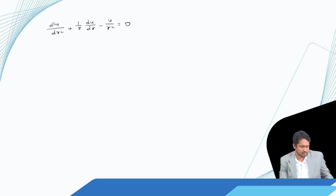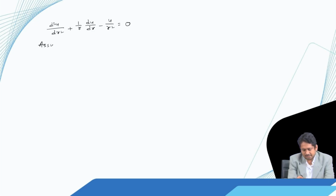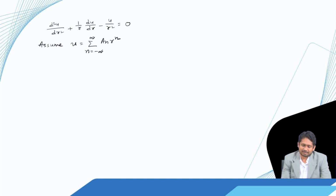Now, we seek an approximate solution which satisfies this equation. For that, the assumption that we make is u as this sum, n going from minus infinity to infinity, a n r to the power n. So, u is a function of r. Because the response is axisymmetric, u is a function of only r; we do not have u as a function of theta, and u is the displacement along the r direction, the radial direction.